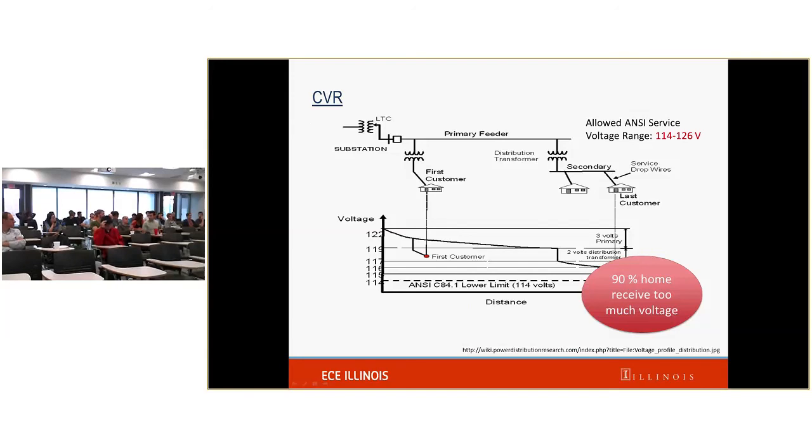Yes, Simi? It would seem like CVR would benefit greatly from reactive voltage support at the feeder, way down the line. Yeah, actually that's our continuing research. The reactive power support scheme is where we try to maximize the benefit of CVR by flattening the voltage profile.